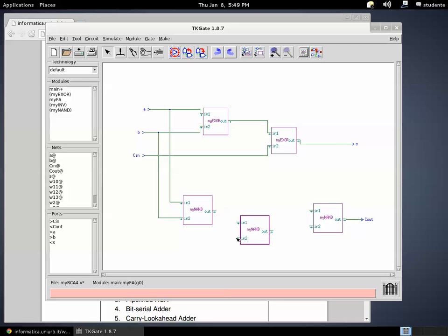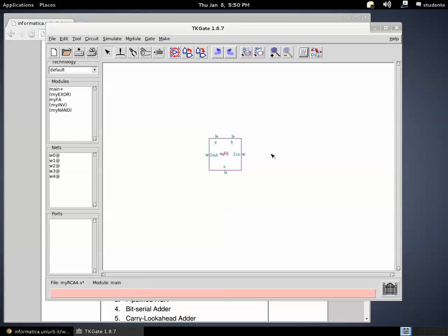At the second level, I have the carry in and the XOR. Then at the third level, I combine the output of the 2 NAND gates into the last one. And here we are. So this is our implementation of a full adder. We can test it before going ahead. So if I go back to the top level, I can add the switches and LEDs in order to test the functioning of this first component, which will then be reused 4 times in order to put together a 4-bit full adder.